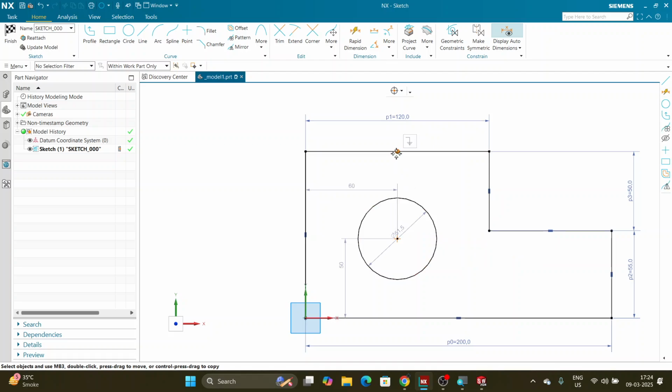In SolidWorks, normally you can't. I'm just clicking it once, a normal click. So clicking the midpoint, you don't have to press Control or anything like that. Remember, because in SolidWorks you have to do that. So we have to press Escape first, make sure nothing is selected, and pick this point and be a little patient after you click, because this window takes a few seconds to appear sometimes.